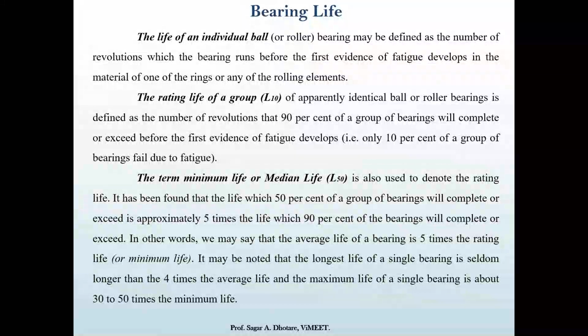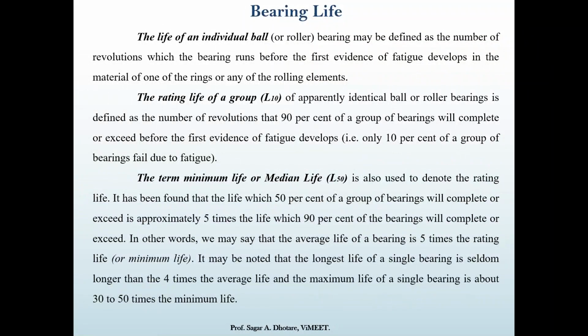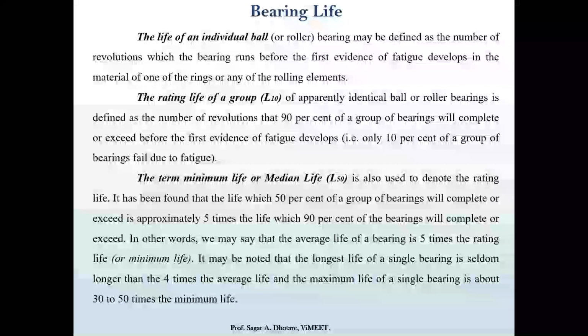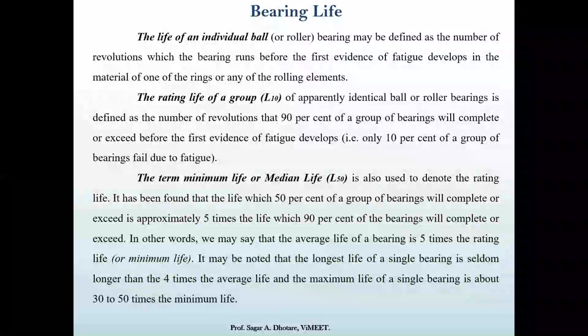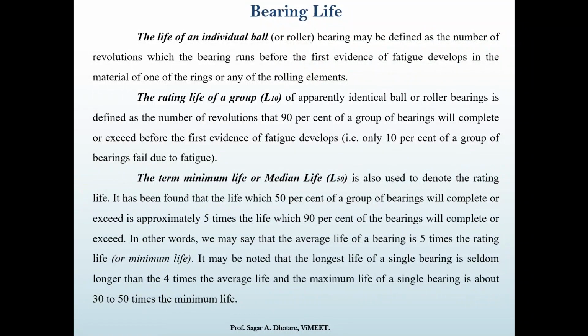Next one is the rating life of a group. We know that whenever we are selecting any kind of bearing, it fails when its life is over. If I say I have selected a bearing for a particular application that should sustain at least 10,000 hours of running condition, and if that bearing fails to complete the 10,000 hours, we can say it is not suitable for the application.